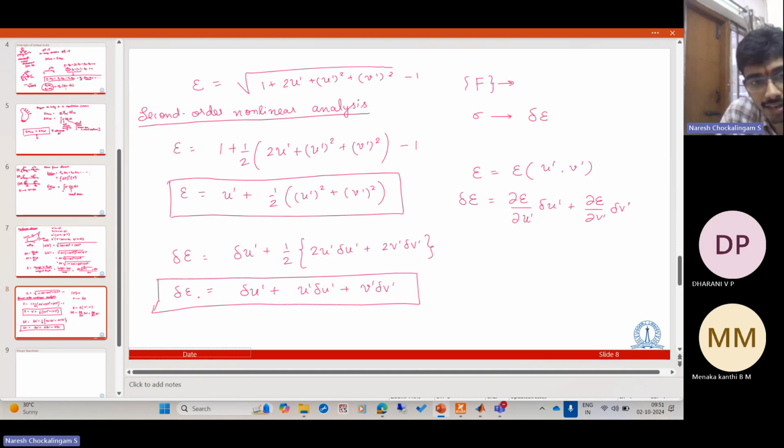So look at the change in strain. This is where the nonlinearity comes from. You already have a body that is highly deformed. Now, if you make a small displacement, which is some del u, that is not going to create a small strain, which is just del u dash, right? This is going to be associated with the existing state of strain as well, not just the increment that we are applying. So the body is in such a state, you make a small change to its configuration. The strains that are induced by the small change in configuration not only depend on the change itself, but also on the current state of the body u. So this is where the nonlinearity actually comes from.